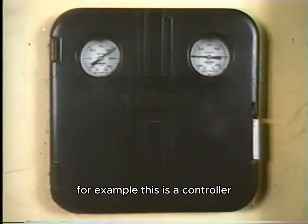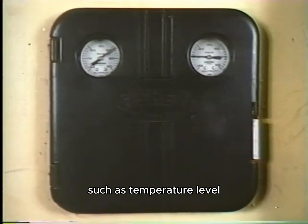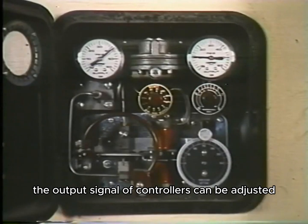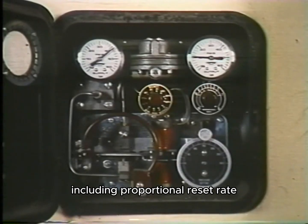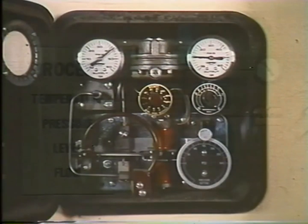For example, this is a controller. It can be used to regulate process variables such as temperature, level, pressure, or flow. The output signal of controllers can be adjusted to provide a variety of control actions, including proportional, reset, rate, or a combination of these control actions.